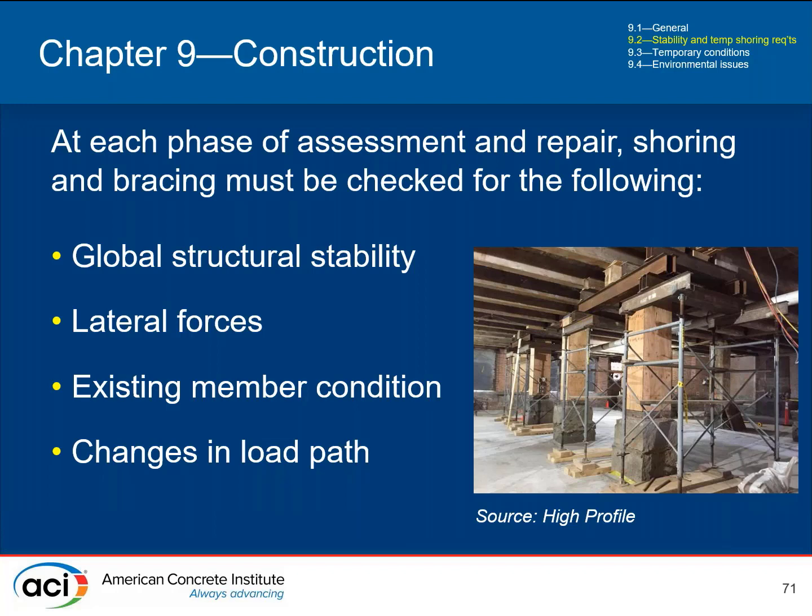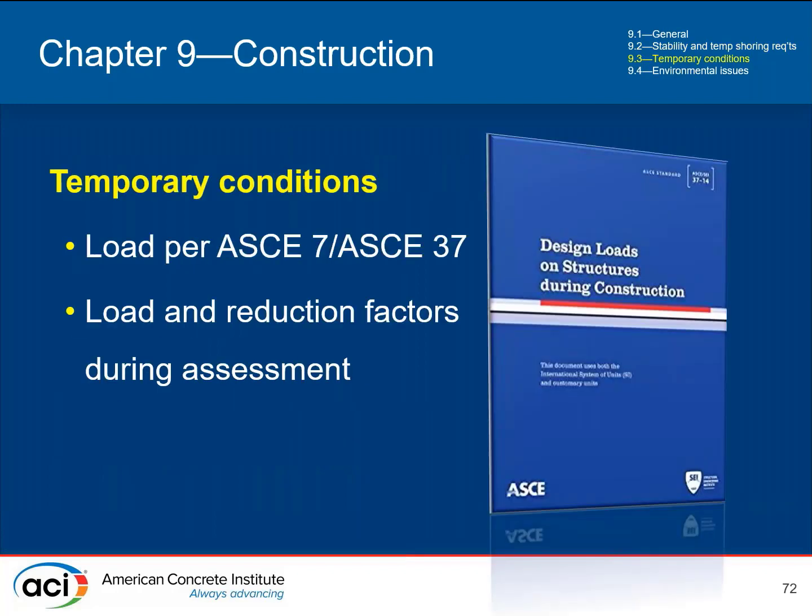They need to know these aspects so they can understand how to deal with it and how that will impact the construction process. But other than that, you need to consider all the same things for shoring: global stability, lateral forces, what you're doing to the load path, all those things that are typical for a shoring project.